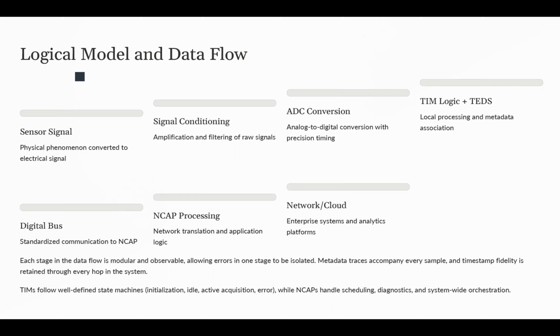After that, there is an embedded processor inside the TEDS, which basically combines that digital signal with some relevant metadata, which comes from the TEDS, like calibration parameters, units, and resolutions. And when we add that metadata to the digital information, the data is transmitted over one of the interfaces that we talked about, from the TEDS to the NCAP.